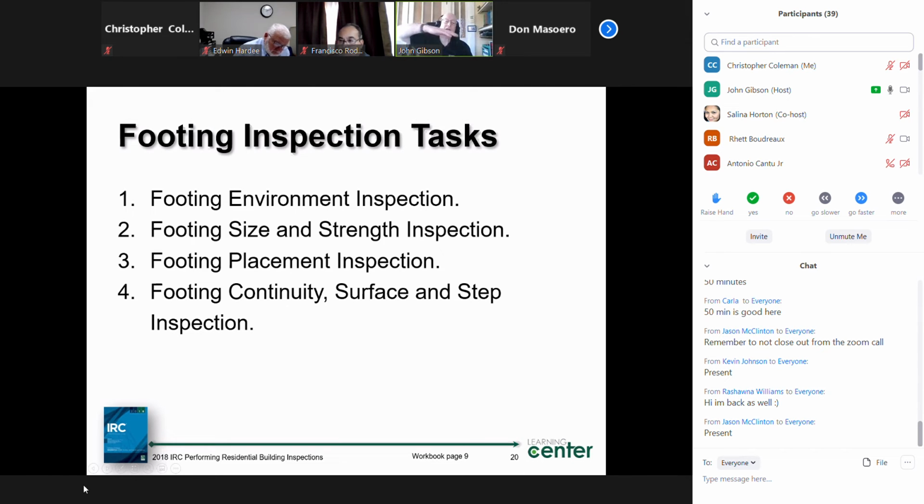If my footing is on too much of a slope, if it's on a downhill slope, now when you put the load of the building on it, it's not coming in perpendicular to the actual footing, it's coming in at another angle to the footing, which causes potential for stress cracks, it causes potential sliding of the building, and it may not be huge cracks or differentials, but it could lead to a failure of those footings in some fashion or another.